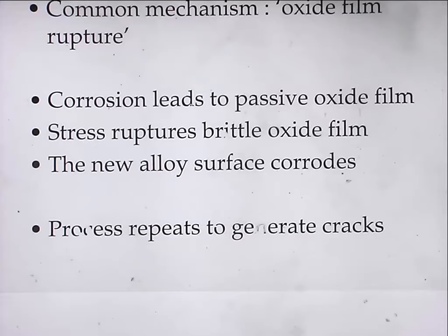exposing the metal underneath. And that's true also for the passive films on iron, magnetite being the most common, Fe3O4. So once you've got a system where the stress is breaking the oxide layer, that's a way of localizing all the corrosion in the point where there is a fracture in that layer.